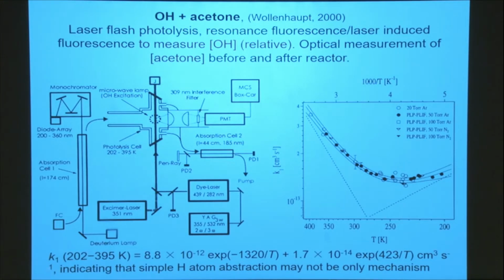For us lot who are using reaction rate constants, here this is expressed as the sum of two standard Arrhenius expressions. And you can see that there are opposite signs to the activation energy in the two parts of that double expression. So in ChemKin, you declare that as a duplicate reaction, and the overall rate is the sum of those two Arrhenius terms, where you've got two different signs for the activation energy.